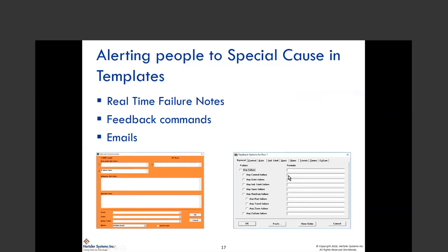And something to remember when you're setting this up is that this code will be executed immediately when you complete the subgroup. Actually, depending upon your configuration settings, it could even be executed every time you complete a single data cell. That's something you need to keep in mind, if the data entry process allows the operator to review the data and correct it before they submit it. One of the things that you can do with this type of command is either directly or indirectly send an email. There is a GainSeeker email command.